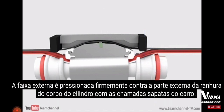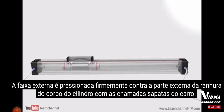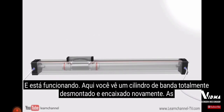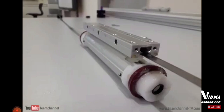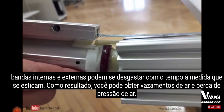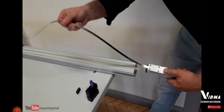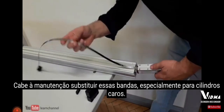The outer band is pressed tightly against the outside of the slot of the cylinder barrel with the so-called shoes of the carriage. And it's working! Here you see a band cylinder totally dismounted and fit together again. Inner and outer bands may wear over time as they stretch. As a result, you can get air leaks and loss of air pressure. It is up to the maintenance to replace these bands, especially for expensive cylinders.